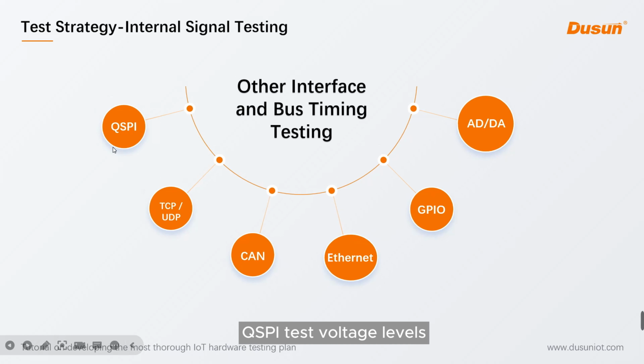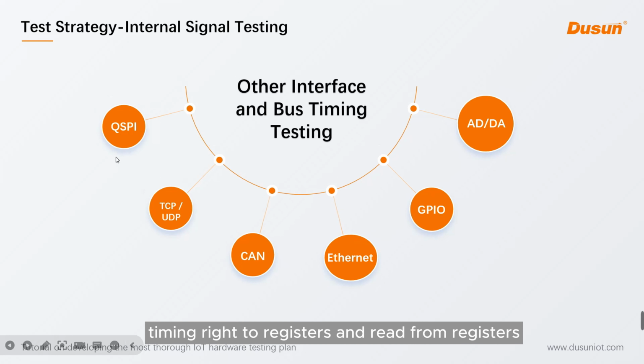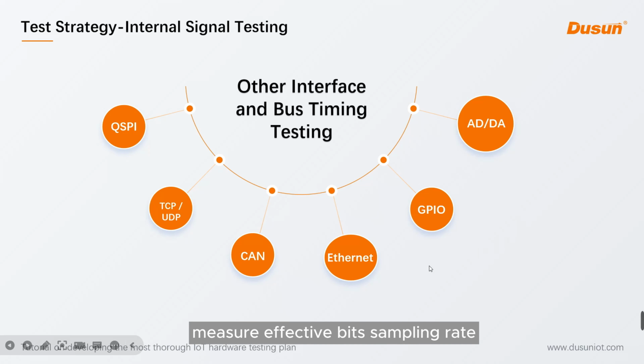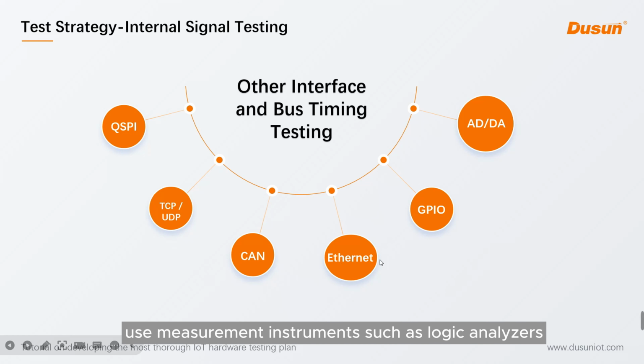QSPI: test voltage levels, timing, write to registers and read from registers. AD, DA: for AD, measure effective bits, sampling rate, signal-to-noise ratio, harmonic distortion, spurious free dynamic range, channel phase error, and bit drift over time. Use measurement instruments such as logic analyzers, power supplies, and ADC testing software like Visual Analog.